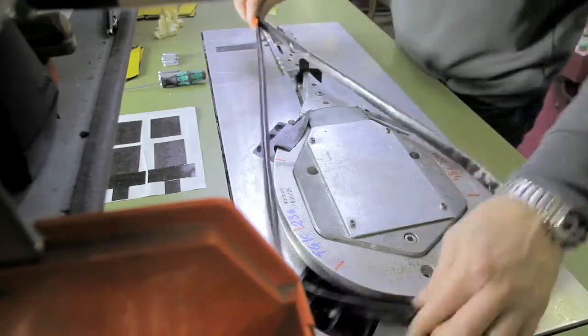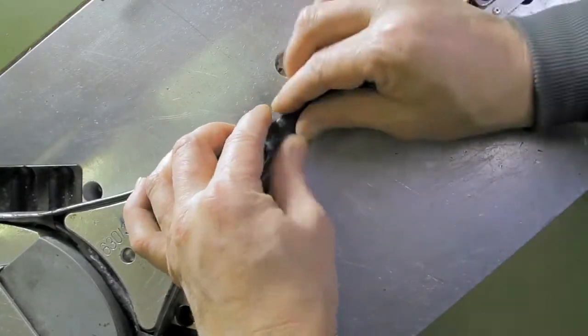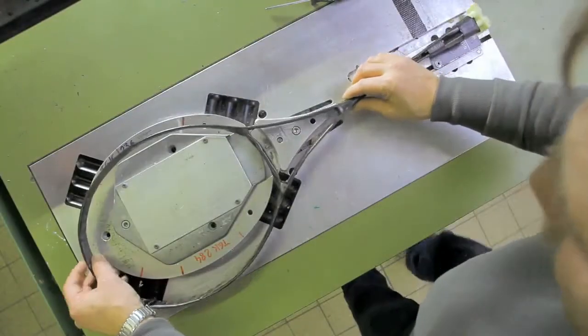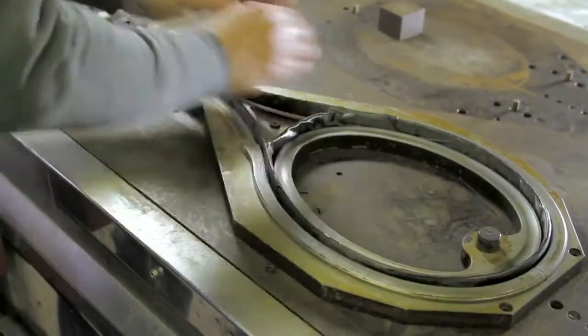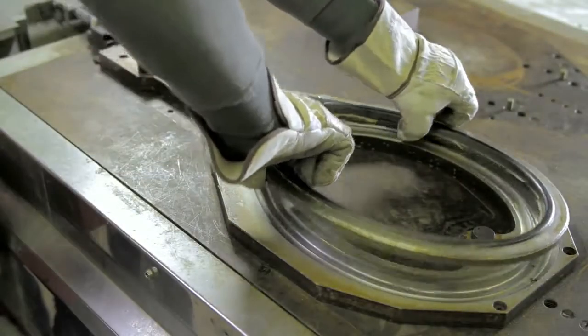In a steel mold, the rolled carbon tube is now formed into the racket shape. More prepreg pieces are added at certain locations to form the racket. The preformed racket is put into the mold, which is heated to 160 degrees Celsius in a press. At the same time, internal pressure of 10 bar is applied to the tube to press the carbon fiber layers outward against the wall of the mold, forming the shape.